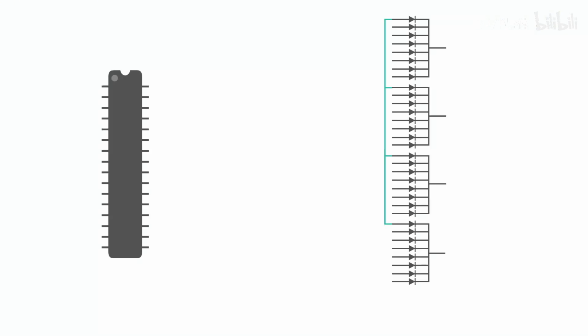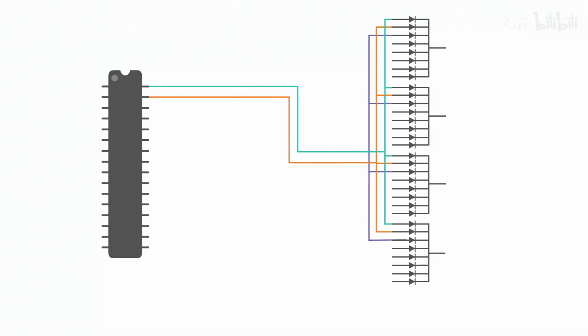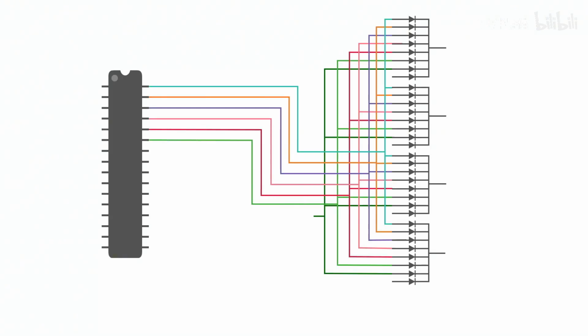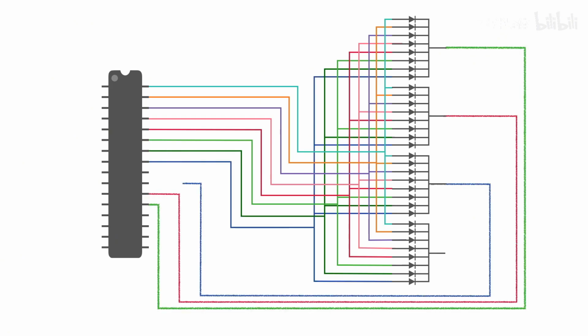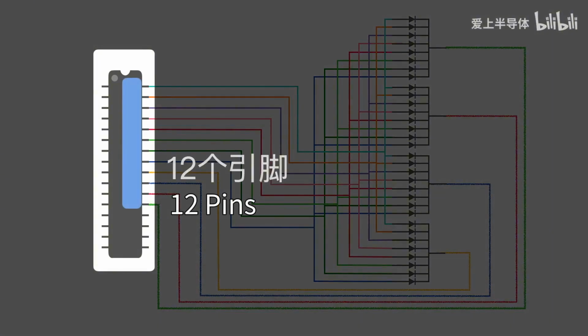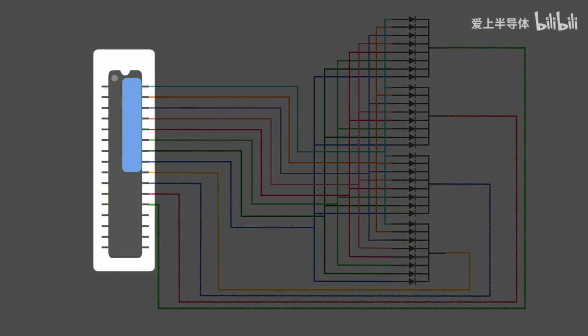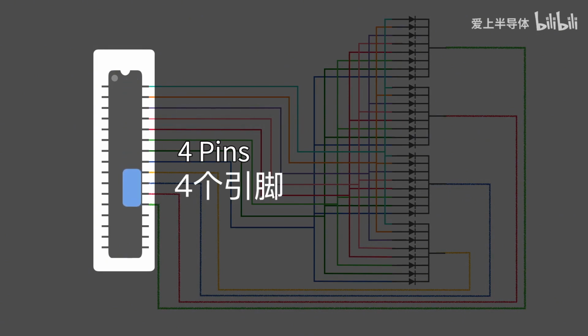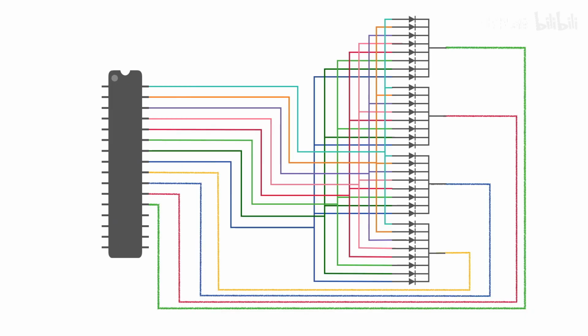At this time, its connection is like this. But only 12 pins are used at this time. The anodes of LED lamps are connected to 8 pins. The other 4 COM ports are also connected to the microcontroller pins, rather than to the ground.